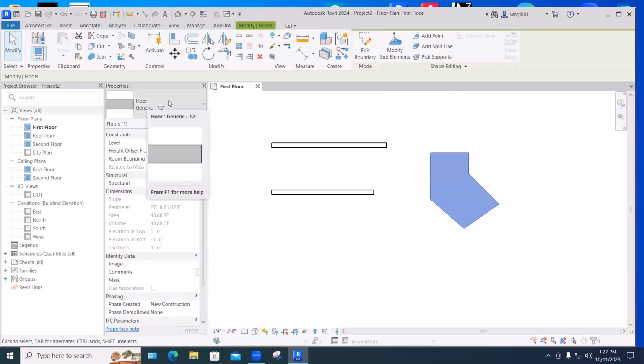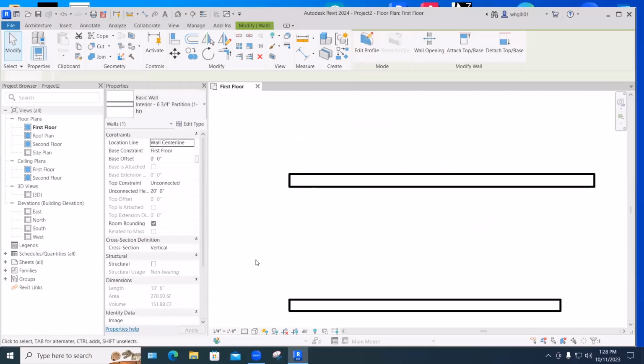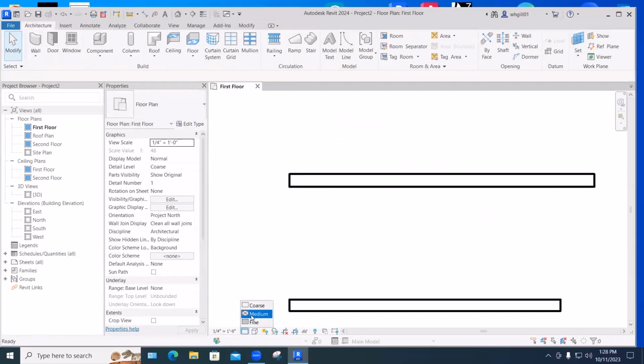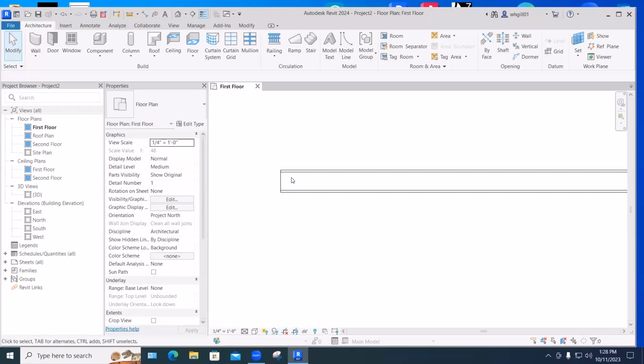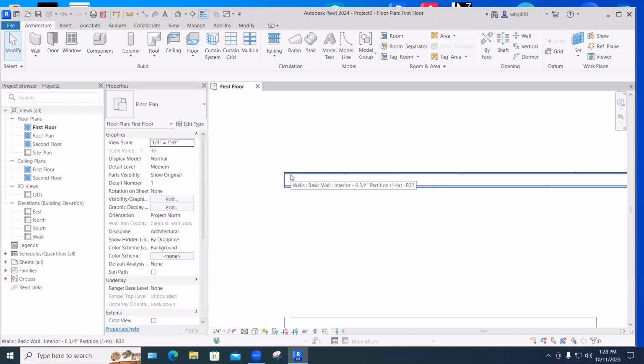And you might be asking, why draw with these generic ones? I spoke earlier about the idea of a line representing a decision. Let me take the walls, for instance. Let's go to medium. We'll deal with all these view controls next class. As soon as I draw a wall like this, I'm starting to imply that I know something about that wall. However wide it is, it's got these 2 thin layers on it. I might really not know what that is. And I don't want to start drawing things specifically until I know what they actually are inside.